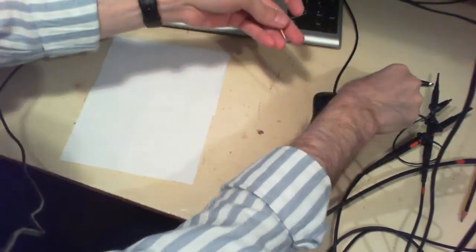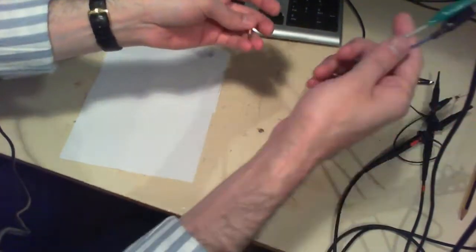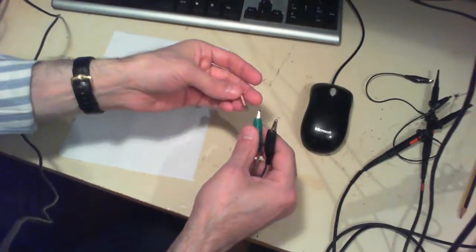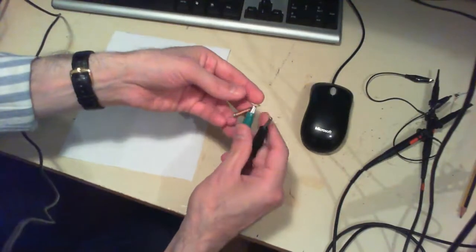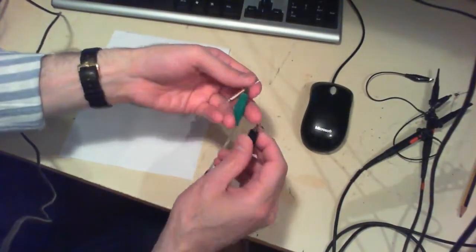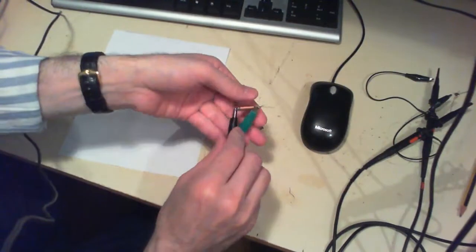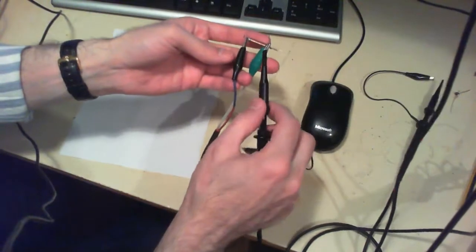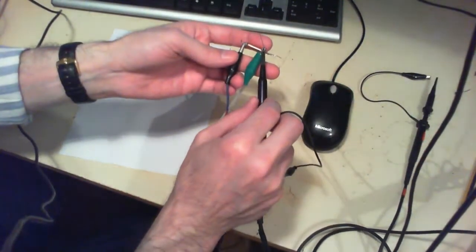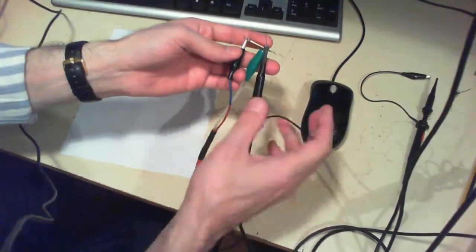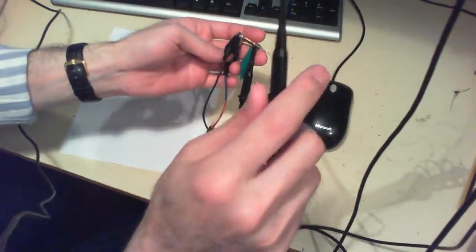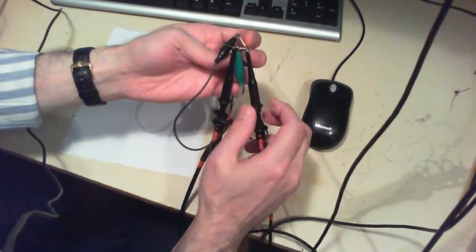This is my circuit, and this is the output coming from the signal generator. I connect the output to the resistor and the ground to the end of the inductor, and this is channel 1 of my oscilloscope. With that I will watch the input, and this is channel 2 of my oscilloscope. With that I'll watch the output.